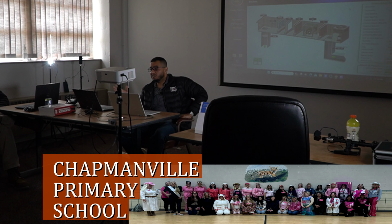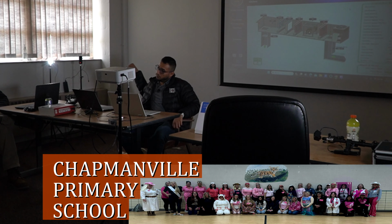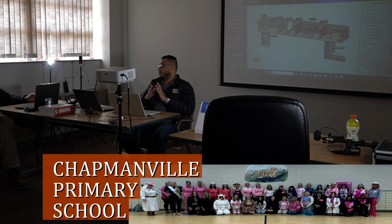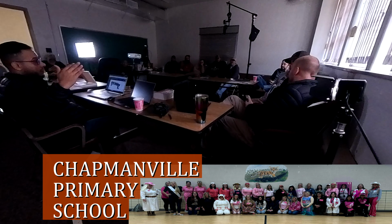You can do the occupied. That's right. And plus, every equipment, by the way, those Chapman primary and Chapman middle, they have an override button on the local wall stat. So since they are individual equipment, if somebody just pushes the button on it, it will run for an override time of 2 hours. That's after hours.